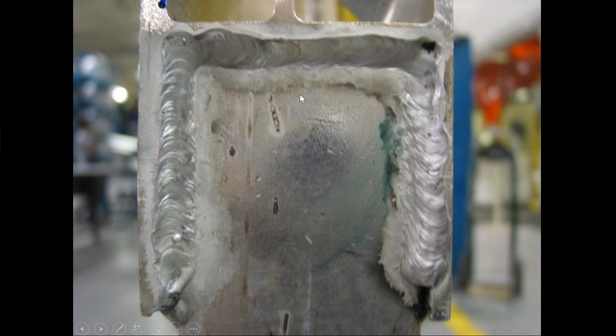Now, again, border samples. Your quality department is going to build you a part that's going to be pristine. It's going to meet every criteria, from welding to locations, quality, sizes, everything for you to reference. So that's where you'd probably find this information. But again, if you don't know, it might be fine just leaving it the way it is. Crater condition. Well, as long as the crater is not digging into the base metal, we know that. And as long as the length of this weld meets the criteria without the size of the crater, you're good. The crater becomes part of the weld size when it becomes part of the weld length.